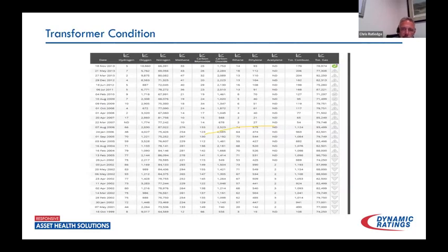We can see that at one point we were up to 2 or 3 parts per million of acetylene, hydrogen climbing, or ethylene climbing as high as 575 parts per million. We have hydrogen. We definitely are generating quite a bit, but again, a lot of that depends on where the sample's being drawn, where the event is happening, is it a nitrogen blanket or is it sealed well? So we do see values up around 90 at times.